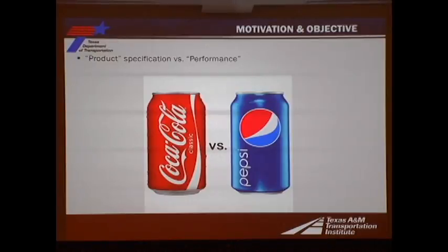But if you go to that CRS2P and it fails the viscosity, for instance, well, that property doesn't really tell you that it's right for the application. If it's supposed to be 1200 and you get 200, well, you know you got a big problem, because that material is super soft and you'd be surprised if you don't have trouble with that material. If it's supposed to be 1200 and you get 1150, what does that tell you? Does it tell you it's a bad material? Not really. Does it tell you you're going to have trouble with it? Not really. What it tells you is just that it's not exactly that product.